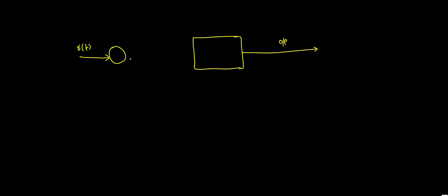Okay. Whenever you give this input, it is not going directly to the plant. In between something is sitting that does the entire job, and that is called the controller. The information from the reference that you are giving goes to the controller, then to the plant, and you get the output. The output may be in the form of a voltage, or a current, whatever it is. That information you have to sense first. That sensing is done by your sensor, and it is called the feedback.